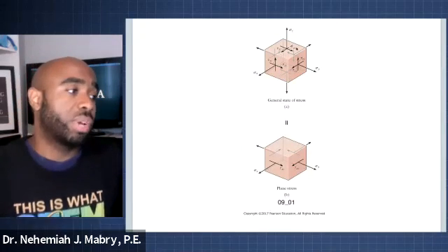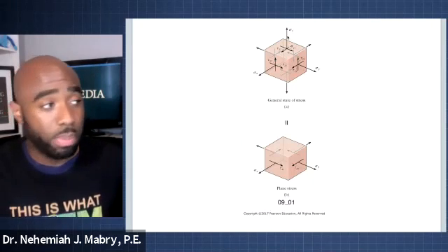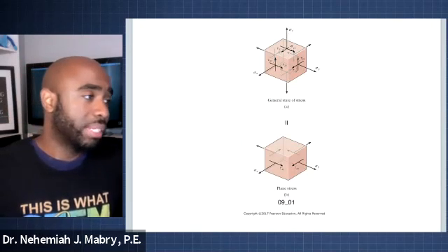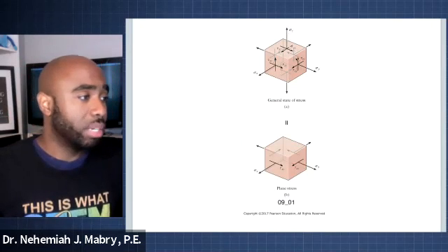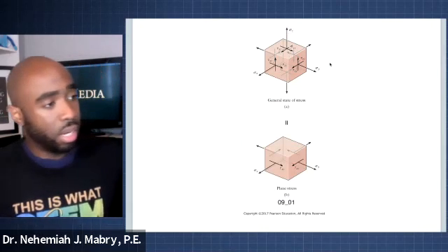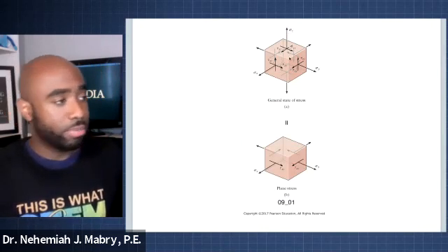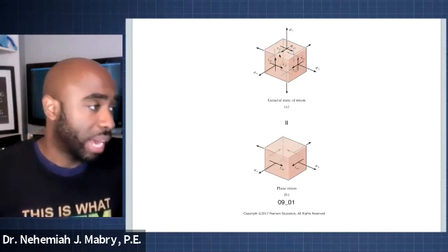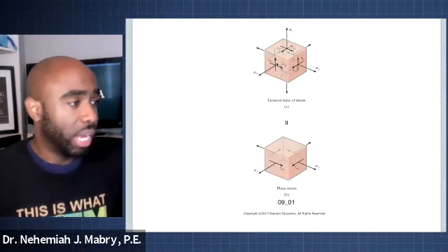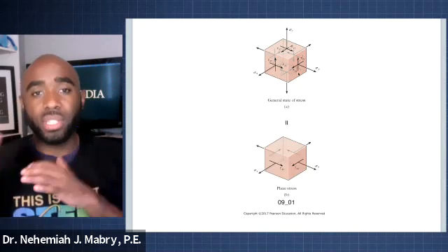And then it has shear stress, which is parallel to its surface, going in one of two directions. So let's take the surface right here at the top. You have the normal stress being sigma sub z, coming out of the z face. And then you have tau sub yz, which is on the surface of z, going in the direction of y. And then you have tau sub xz, which is on the surface of z, going in the x direction. And so forth on every single face.